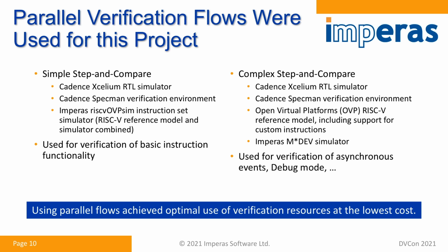In our project, we used parallel verification flows. We used a simple step and compare flow. The tools used in this were the Cadence Xcelium RTL simulator, Cadence Specman verification environment, and the Imperas RISC-V OVPsim instruction set simulator. So in this case, combining the RISC-V reference model and the simulator. And this was used for verification of the basic instruction functionality.